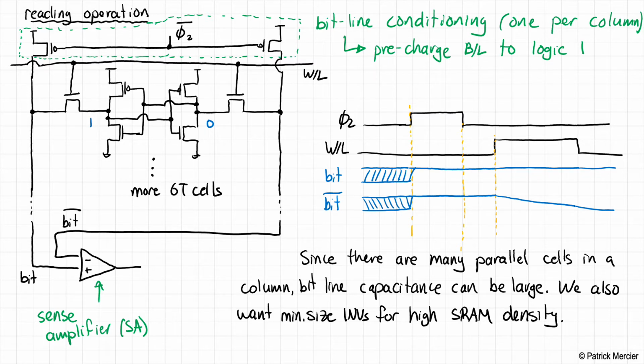In fact, most process design kits allow you to break the design rules just a little bit in order to make SRAM cells even more dense than they otherwise could be. They're very regular structures, and so the first circuits that people tend to build in new process technologies tend to be SRAMs, just to push the process limits a little bit.